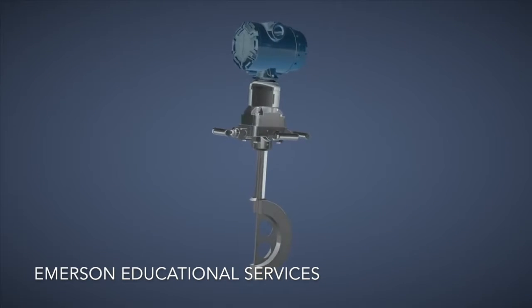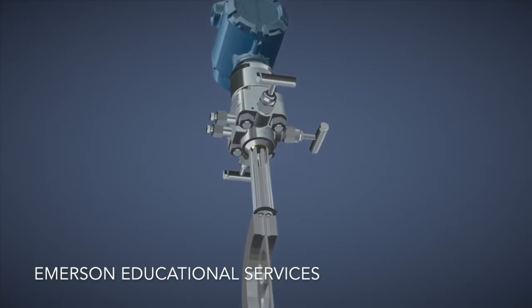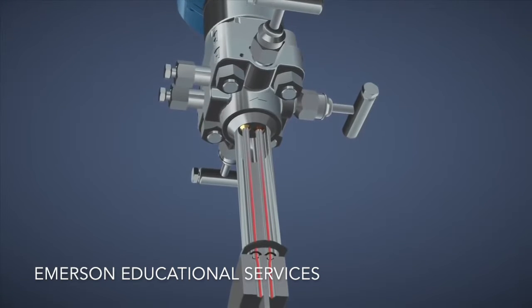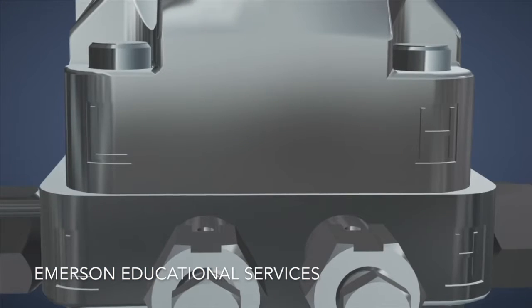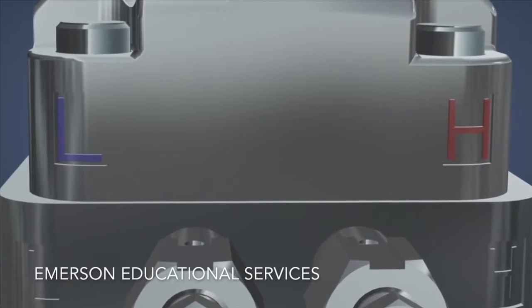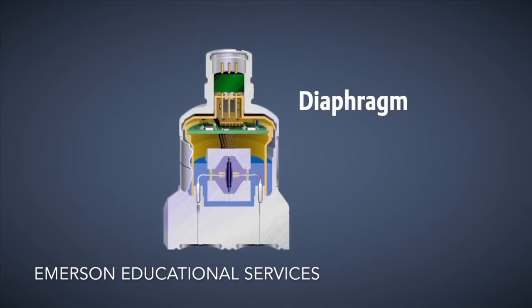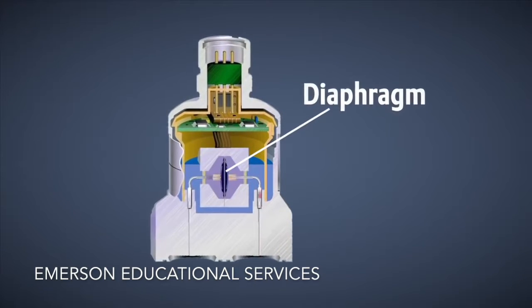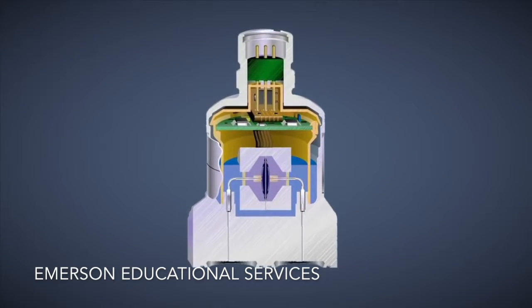The impulse piping of the integrated flow meter runs from the process through the primary element to the sensing diaphragm of the transmitter. On one side of the transmitter is the high pressure side, on the other, the low pressure side. The diaphragm deflects relative to the pressure change from one side to the other. It is very sensitive and can detect very small changes in pressure.